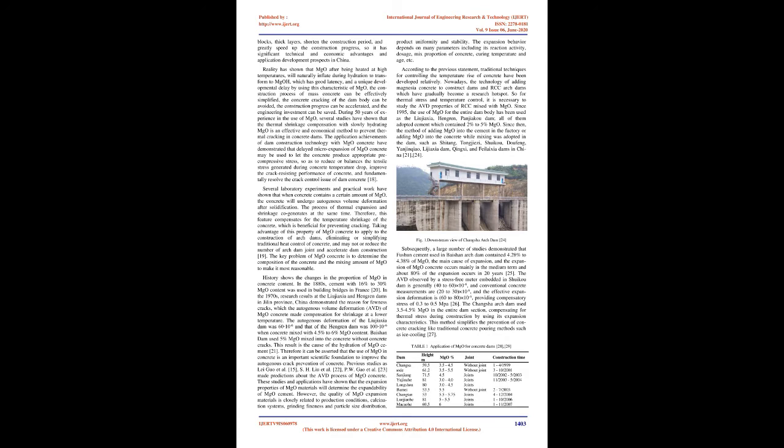In order to control the temperature in concrete, some typical methods are used, including using the cooling water pipe, pre-cooling aggregate, increasing construction time, adding fly ash, and other traditional temperature control methods. Although these methods contribute effectively to the control of concrete temperature in the dam, they increase construction time and cost money. Therefore, scientists have been continuously looking for new methods to prevent concrete cracks, including the addition of MgO-type expansion agents that can compensate for shrinkage of concrete and relieve the cracking risk.